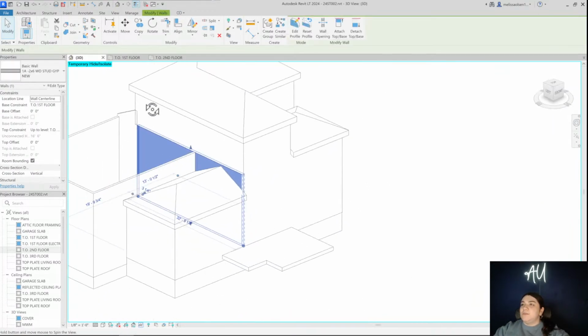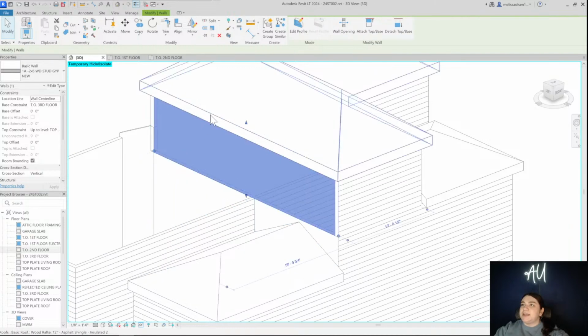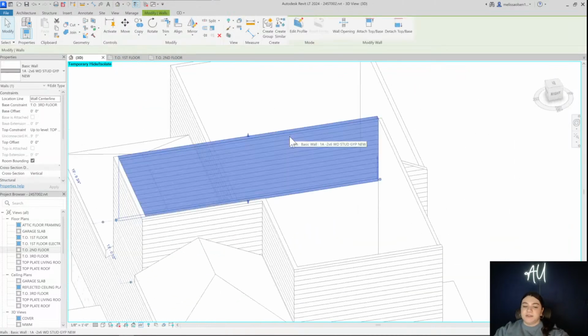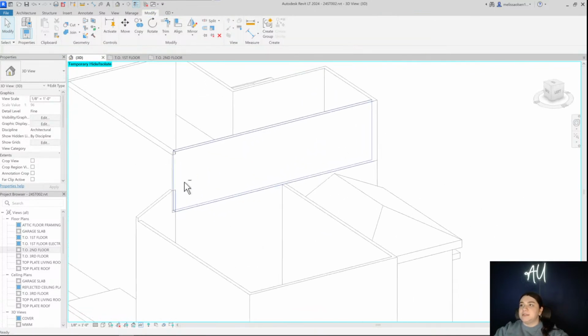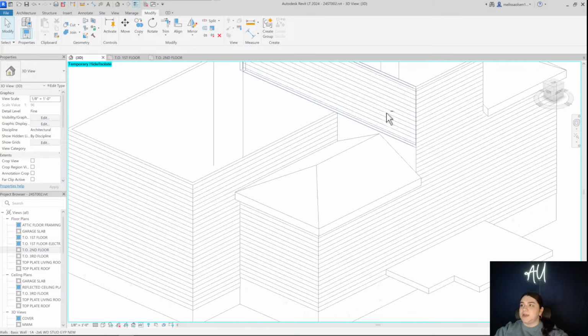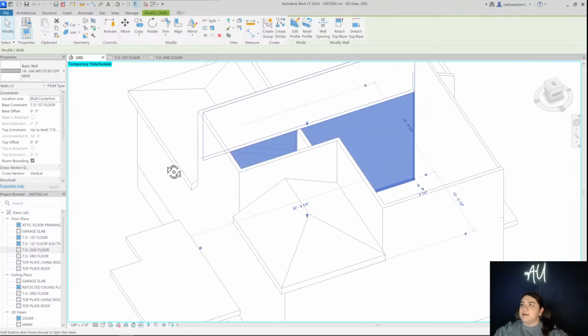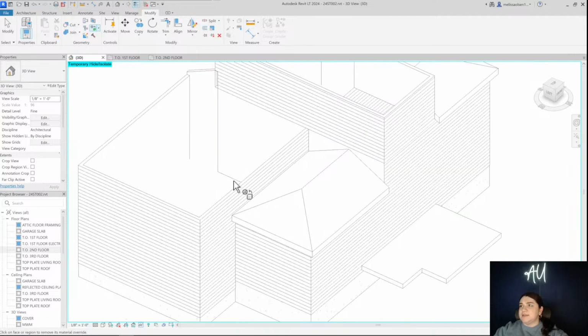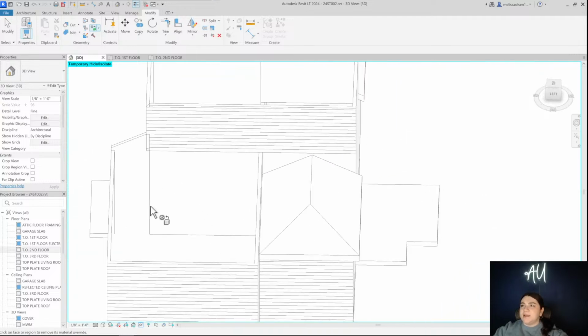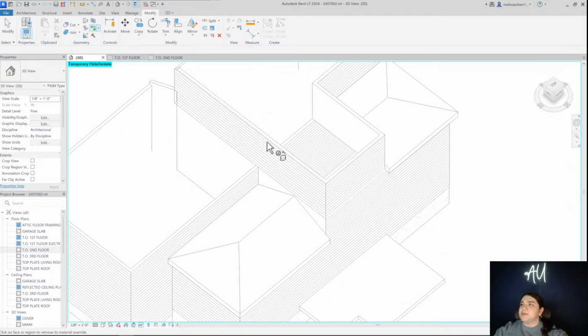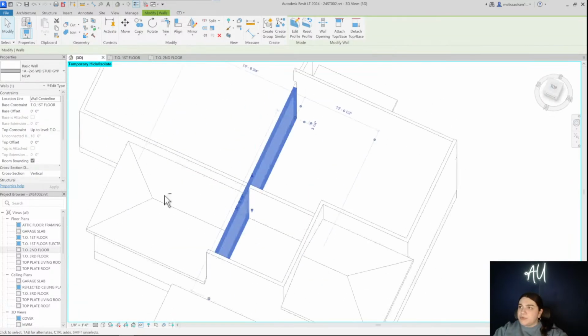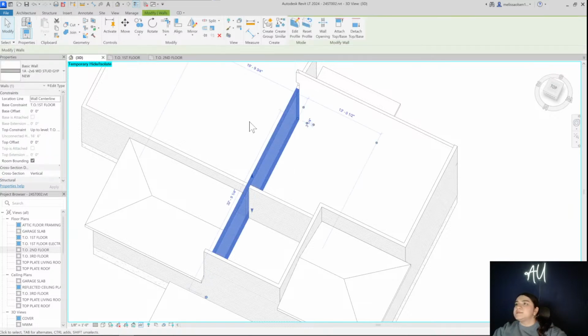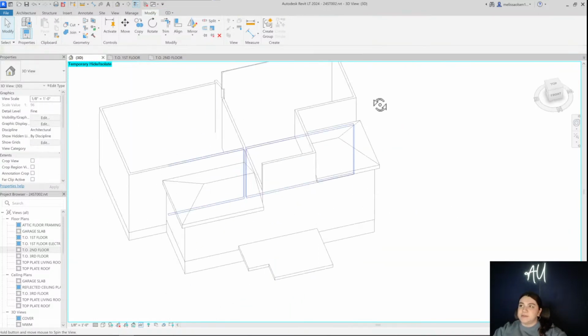So this as well, we have to change to be our exterior. So I'm going to hit the space bar and just flip that wall out so that the exterior material is the one that's showing. And then this one here looks like I also painted it. So I'm just going to remove the paint for now. And what that's going to do is bring that horizontal siding back, which this is just temporary siding until we really start designing it and figuring out what we want to do. Why isn't that removing? Okay, it did, but I'm going to flip it so it's on that side.